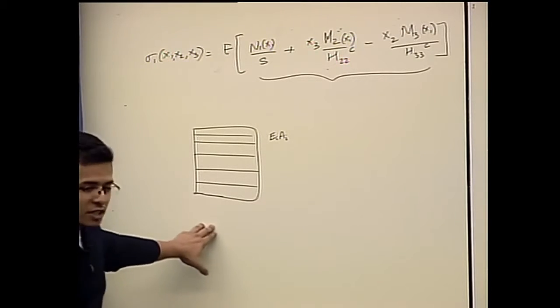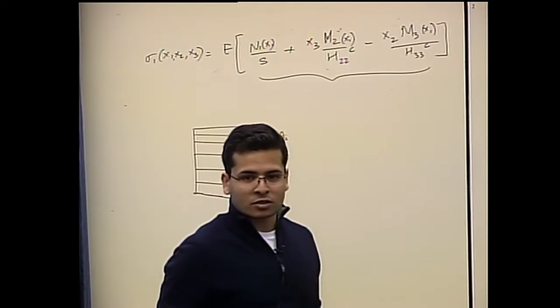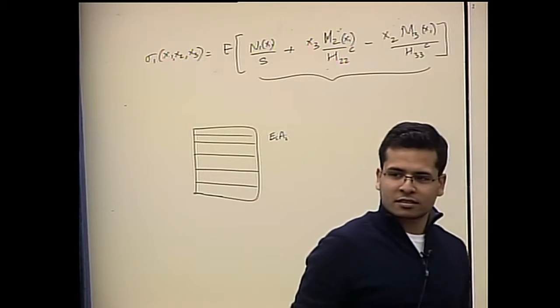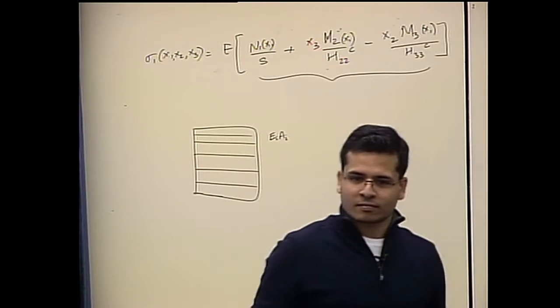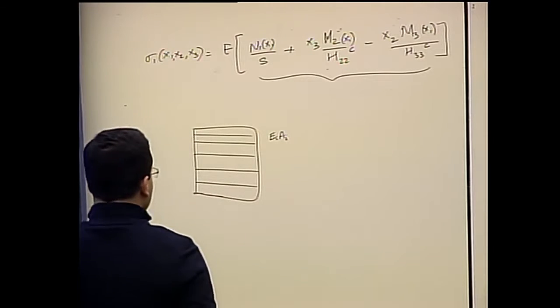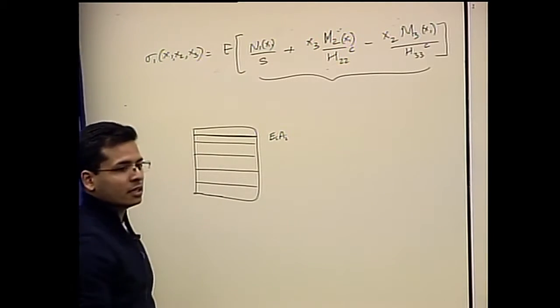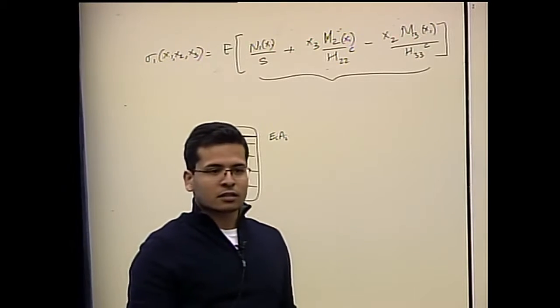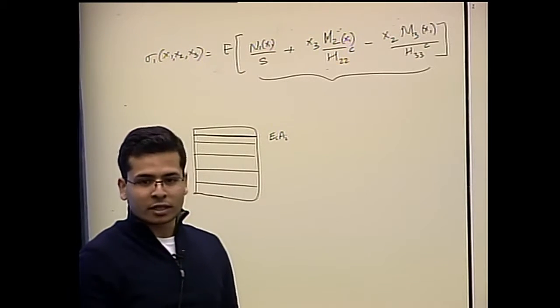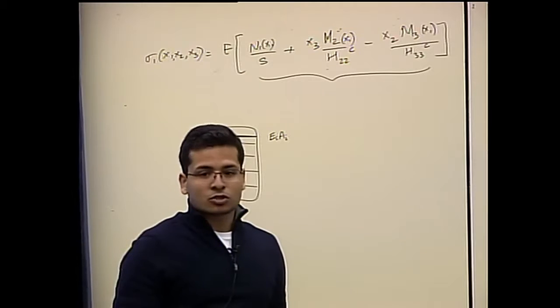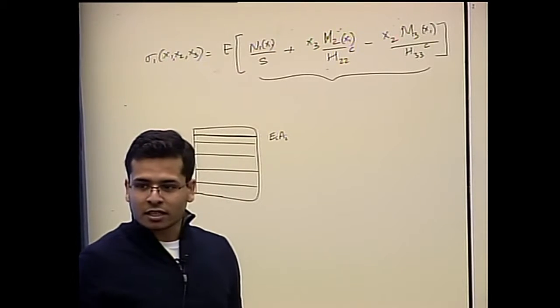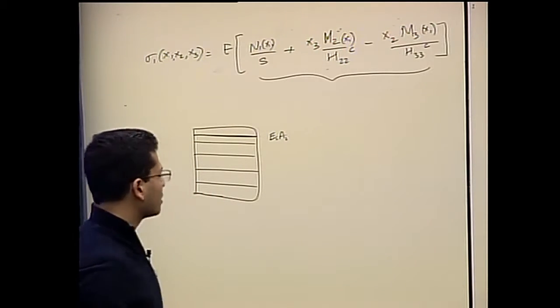Okay, so the strain would be continuous and the stress discontinuous. Why is that? You can't have delamination between the layers. Assuming this layer is bonded to the other layer with a perfect bond, there is no delamination between the two layers. So strain, being a kinematic quantity, has to be continuous.